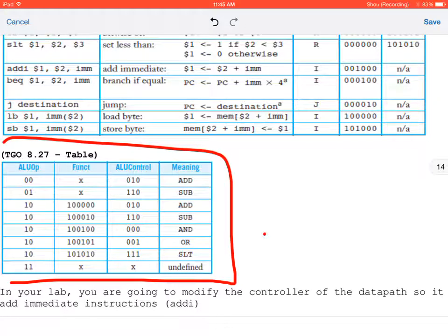What happens is, instead of 4 bits, it's 3 bits out from the ALU control in this particular data path. And it's addition. If it's 0, 1, it's going to be subtraction. But here they've actually included a sub-I value instruction. If you recall from 385, they took this out and just used 2's complement to reduce that. Here, they just put it in because it's 8 bits, so it's actually significantly reduced anyway. So now, if it's 1, 0, this is what the ALU is going to receive if it's an R-type instruction, which means it now uses that plus the function value coming in to determine.